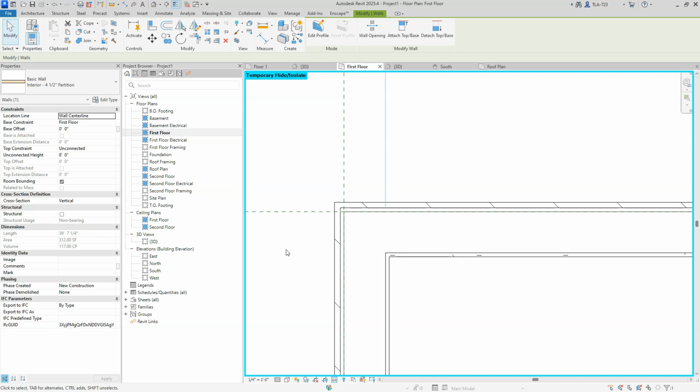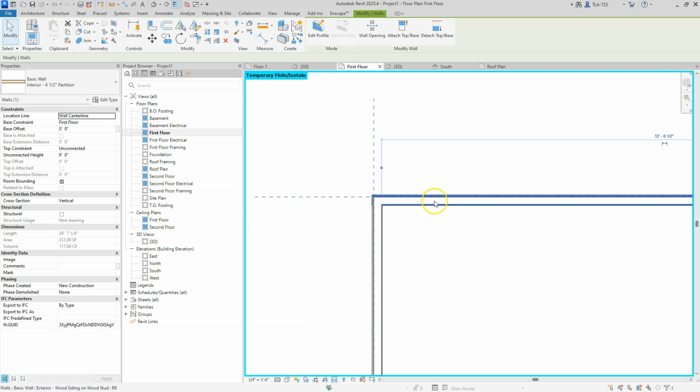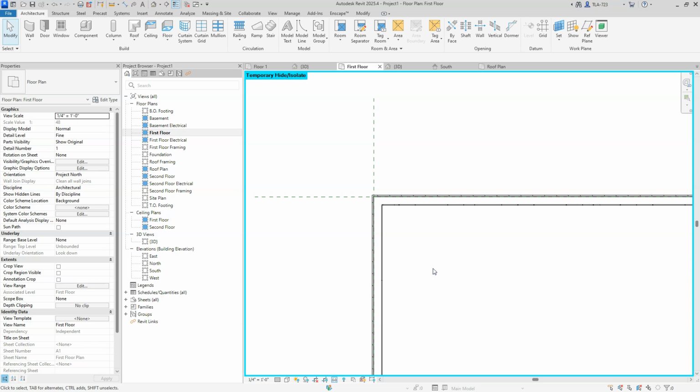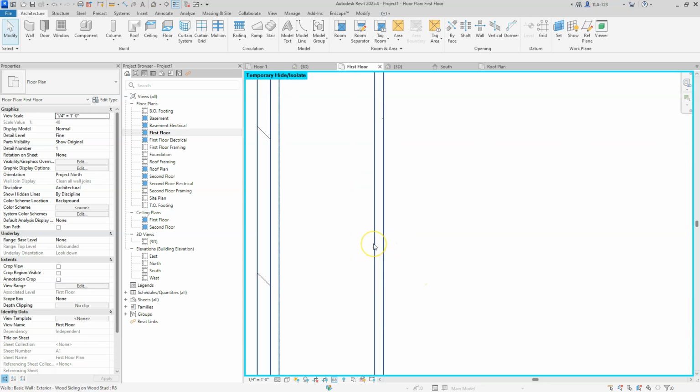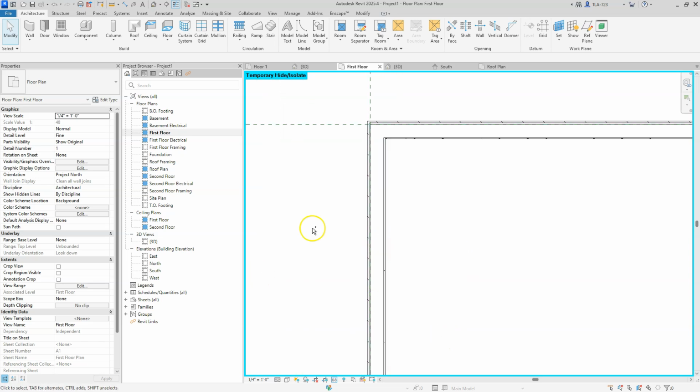It just cannot read your mind. In fact, it just feels like it's working against you sometimes. So make sure that you know how to override Revit, and tapping that tab key is pretty universal across a lot of different commands in Revit. If you need to select something, if you tap the tab key, it's going to highlight that thing usually.